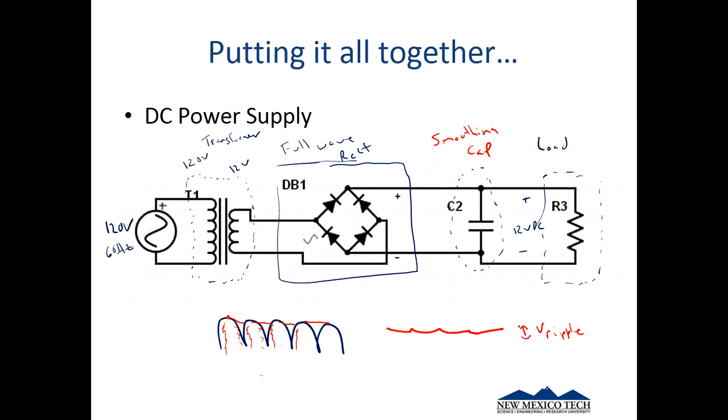We could put a really big capacitor in your cell phone charger and have almost no ripple voltage. There'll always be some, but it would make a really tiny ripple voltage, except then you'd have to carry around this big capacitor. So it's always a compromise as to how much ripple voltage you can allow and how small and compact you can make your charger.